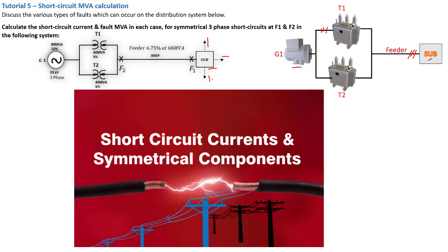And all of a sudden, you've got more loads connected that were not supposed to be connected to this substation. So what will happen is this feeder will be overloaded. And that can also create a situation that is not pleasant, which is also a fault. So those are some of the things that can occur, but obviously many more things can happen.